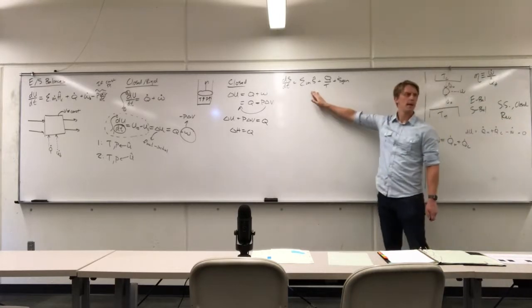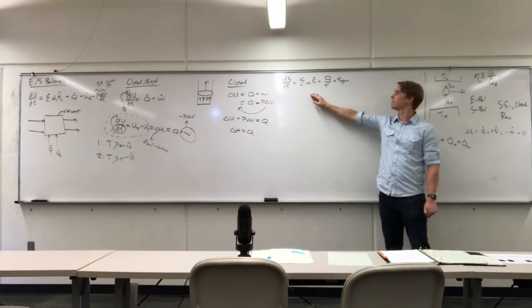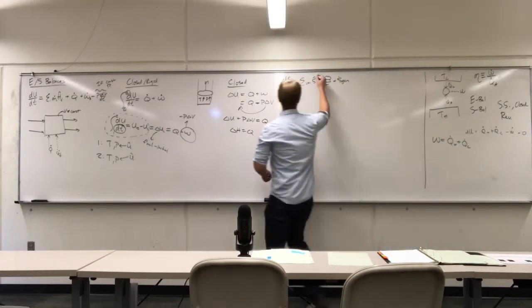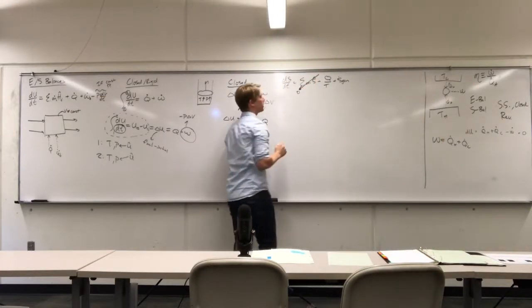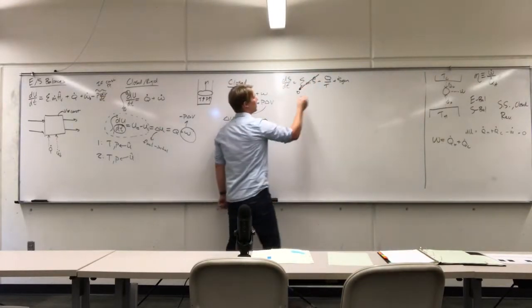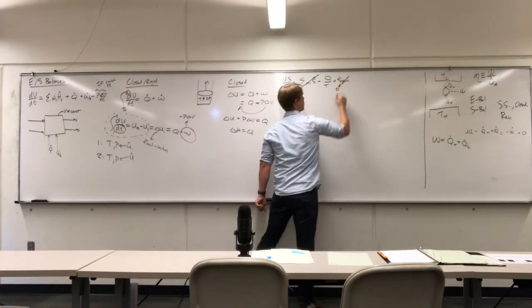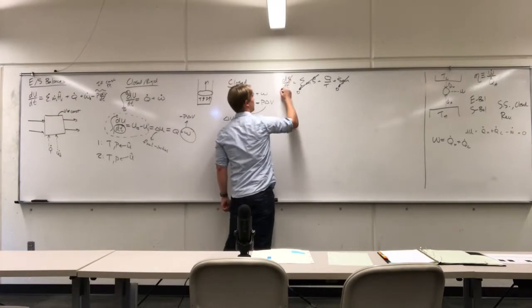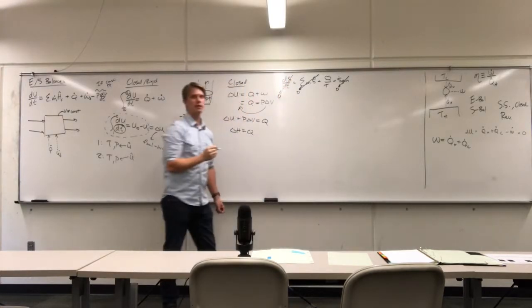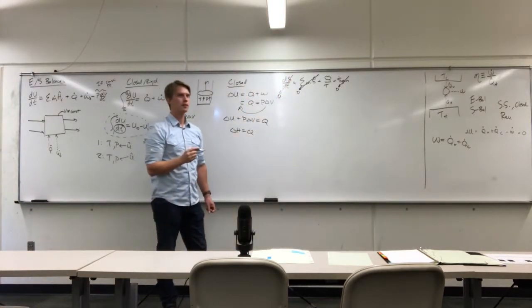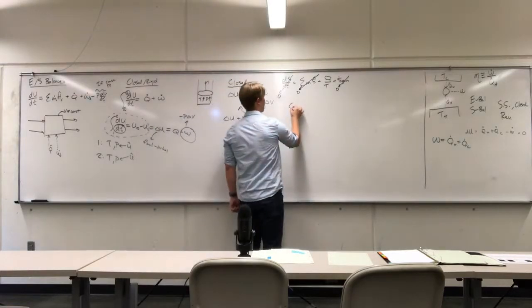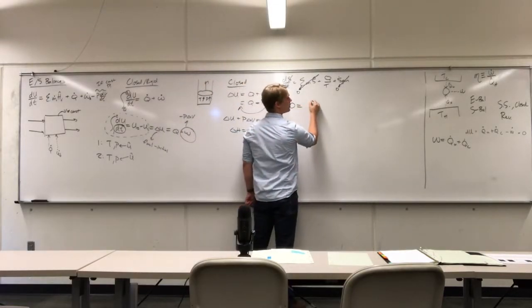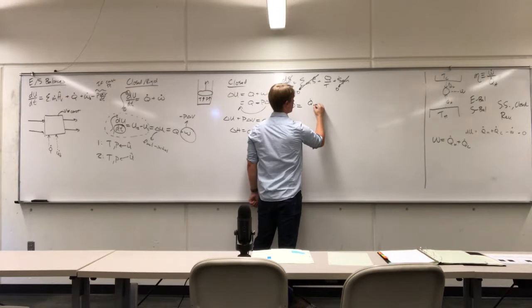Which terms go away? The mass term goes away. There's nothing coming in here. What else goes away? The S gen. It's reversible, so we have no entropy being generated. And steady state, so this goes to 0. So Q_H over T_H, 0 is equal to Q dot H.